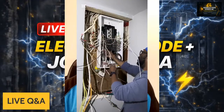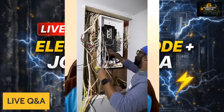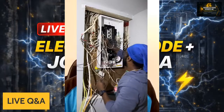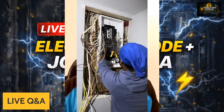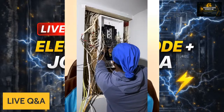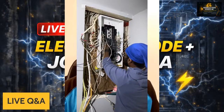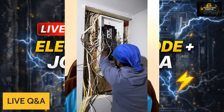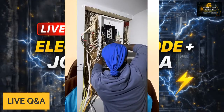The first half of this live stream was about conduit installation: about 4-bend saddles, shrinkage, how when you bend offsets you lose some of your pipe, the shrinkage happens, your 90 stops, the 6-inch 90 stop, and so on. That was covered here in the live stream tonight.